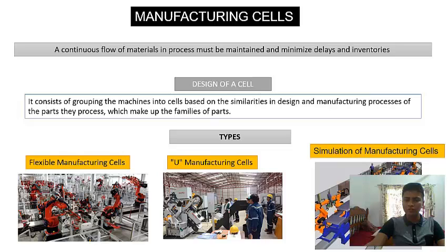To reduce processing time and use of resources, it is about carrying out operations in takt time, for which it is necessary to change the traditional arrangement of similar machines grouped in process departments, such as milling and turning, to manufacturing cells in U-shape, integrating the machines with personnel with multiple skills, tools, spare parts, materials, components, and facilities necessary to manufacture a family of products per cell through group technology.